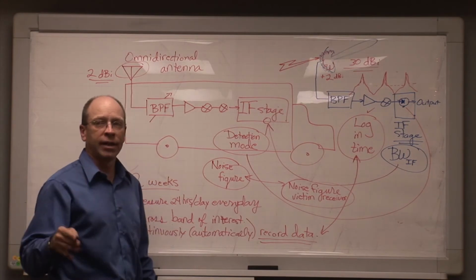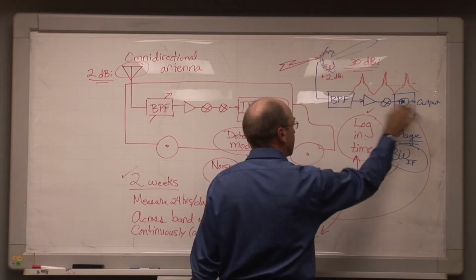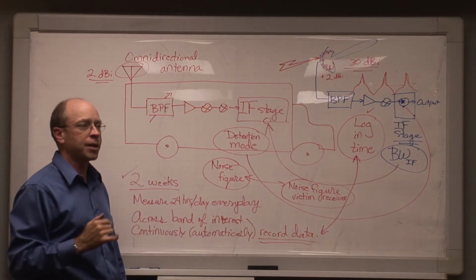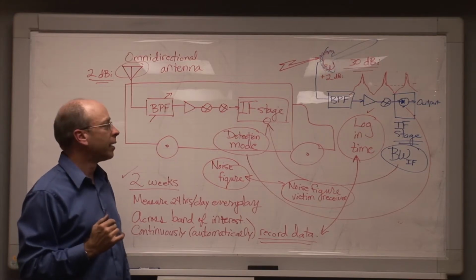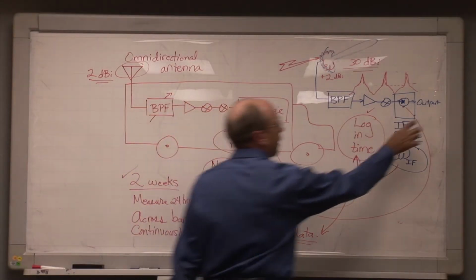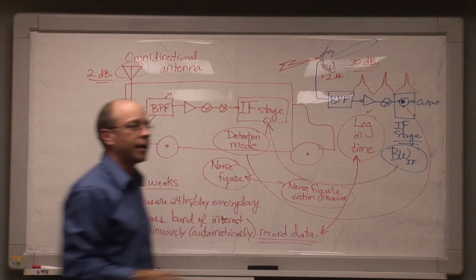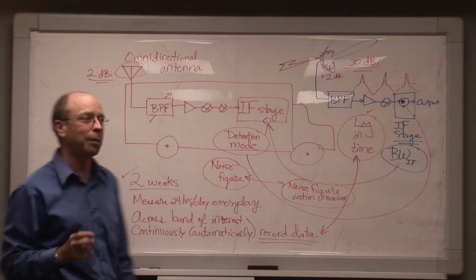And on that one, we actually finally went back into their receiver. We actually opened it up. We actually looked into the receiver, and there's a photograph of 2 of our guys, Bill Kissick and Brad Ramsey, actually doing this at a hilltop site in one of our old technical progress reports. And we basically finally established that, in fact, they had a dropout in their data links at this output stage. It turned out that the data was going into a sort of a bit bucket due to a software problem.